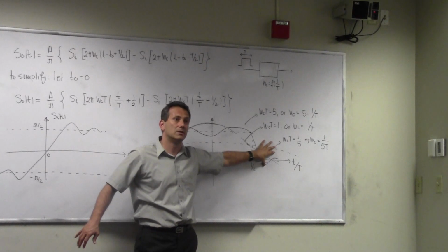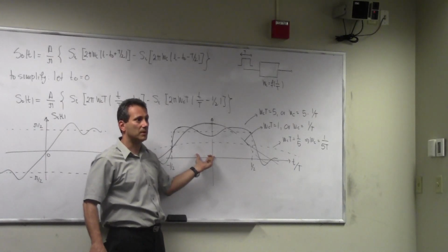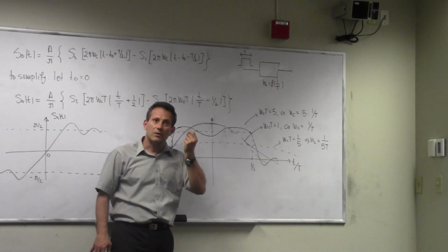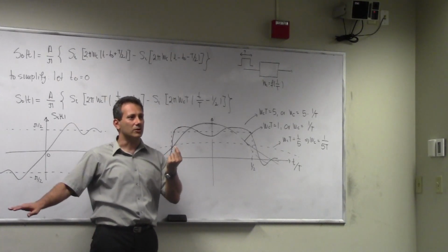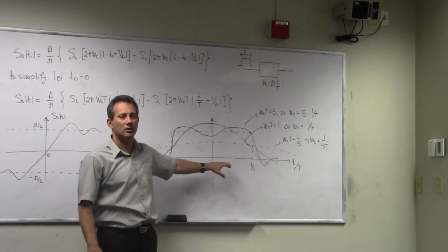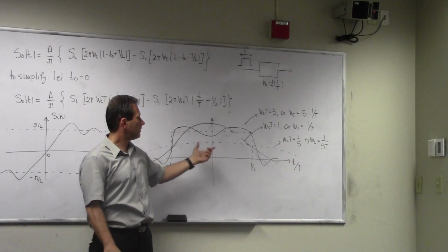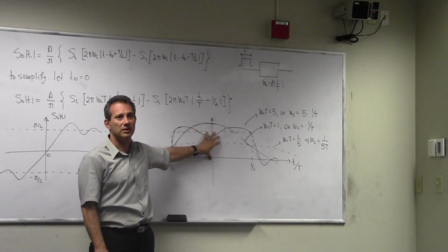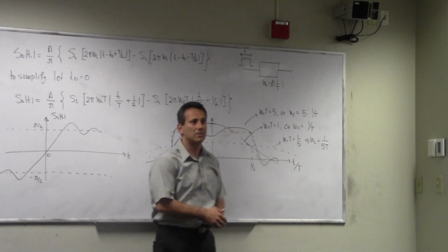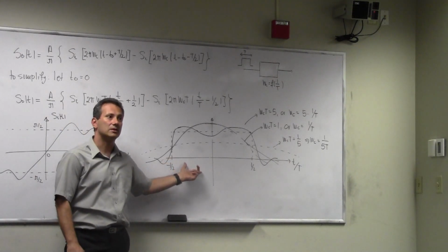And what that does is it corrupts the adjacent symbols. What do we call this? We call this intersymbol interference. Because this symbol here, because of its dispersion in the time domain, interferes with this symbol and interferes with the previous one, right? So now, if you look at what happens in band-limited systems, forget about noise. I'm my own worst enemy, right? Even if I increase the power to the point where the signal-to-noise ratio is really good, your signal is strong, and noise is very weak, the fact is that you're interfering with yourself. This bit here affects the next one, and the one after that, and potentially several bits to the left and to the right.